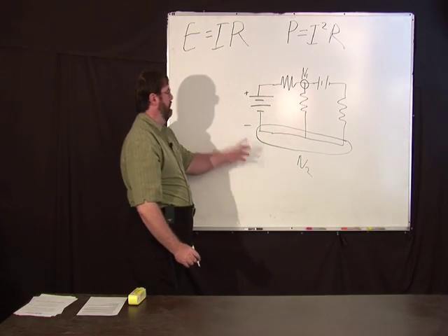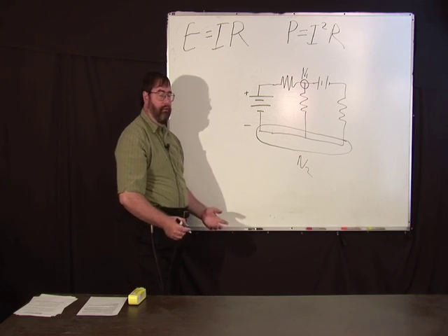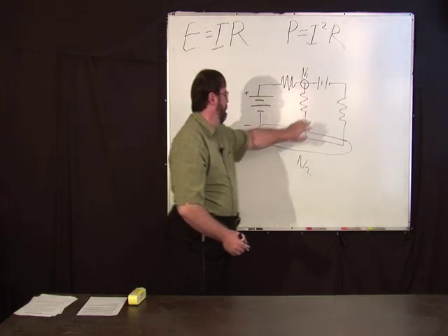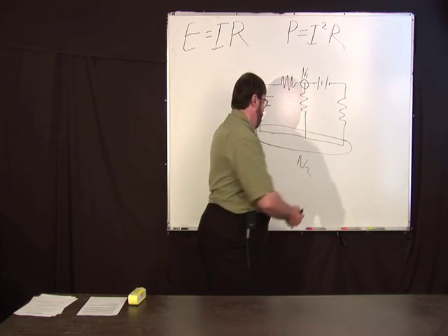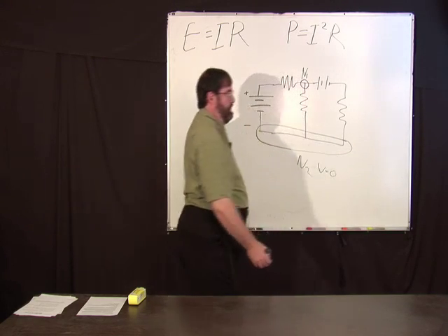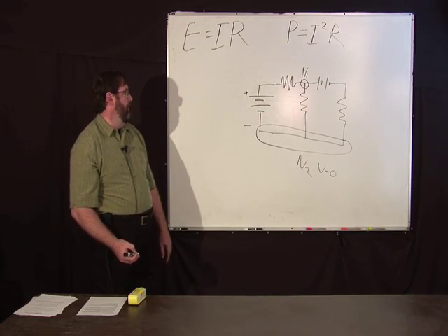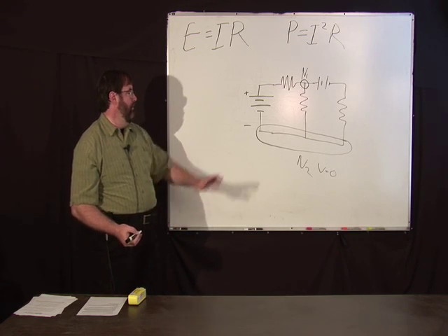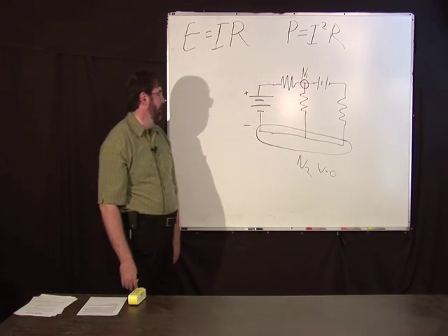Okay, and those were places you can get voltages. Those are principal nodes. You could have other nodes, like if you wanted to know the voltage here, and you pick one as a reference. We'll call this the reference node. We'll call it voltage equals 0, because you need to have some reference. Okay, so now that we've done that, that's places we want. Nodes are places where we want to know voltages. Well, we can figure that out later.